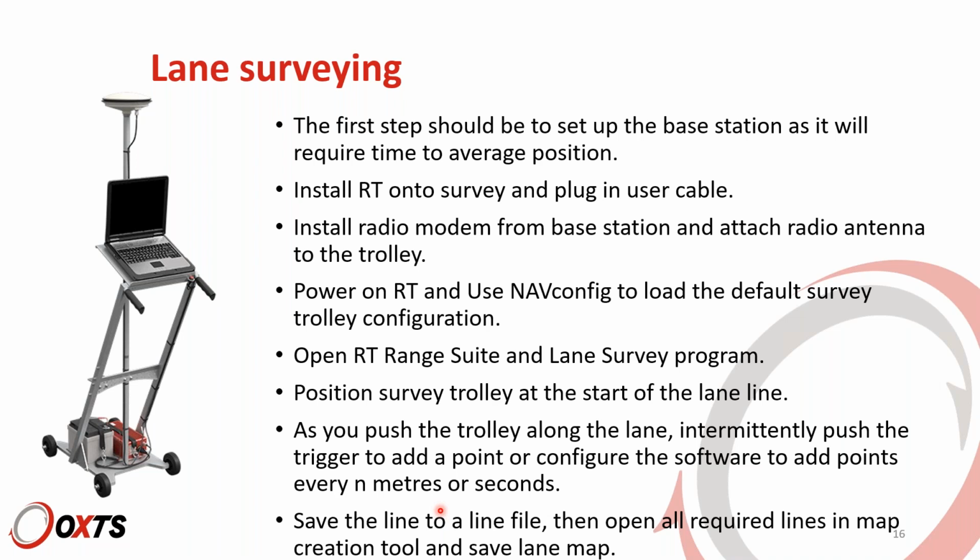Otherwise, you need to detect the true path of the line. If you do have a slightly strangely painted line, that's what the vehicle will pick up, so you do still need to survey that in and perhaps use more points to define that. And for a curve, you'll want slightly more points as well to get a nice smooth curve.